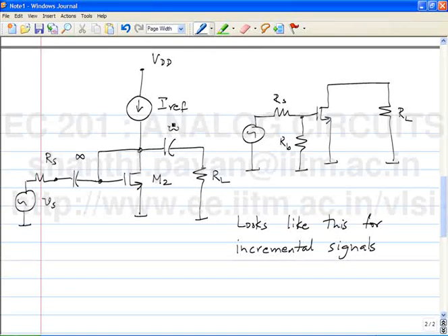Great. So, we all realize the source of the problem. Why is this not giving you any gain? Because the drain and the gate are shorted. So, any smart engineering solutions to this? One good solution, though not practical, is to have, so why do you say inductor?